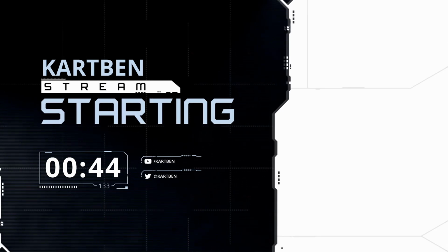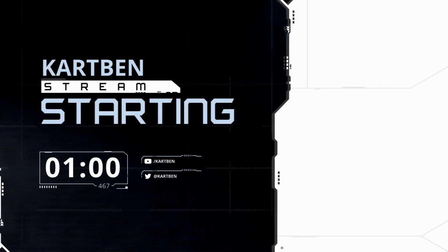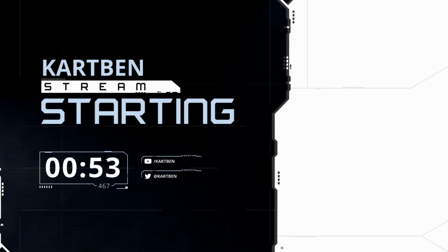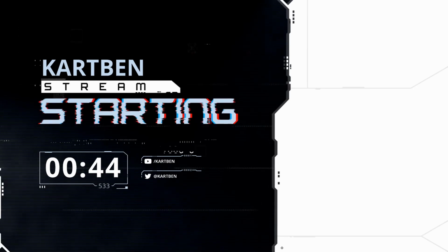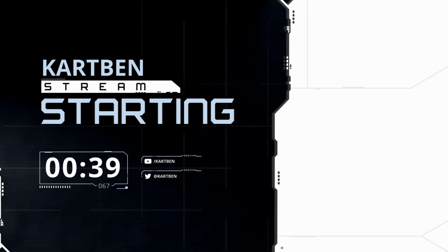So one thing I'm going to try is, let's go back to this one. And since it doesn't have non-manifold edges, we're going to export in STL. And this might just do the trick. STL being a format that's more meant for 3D printing. And so by construction, it might actually be able to avoid the issues that we have.